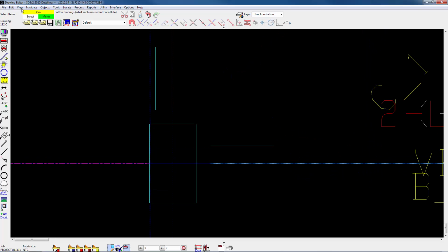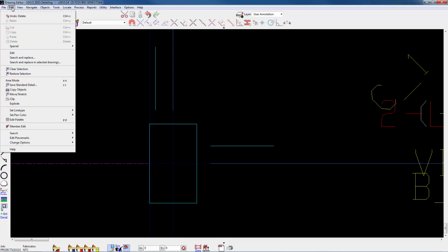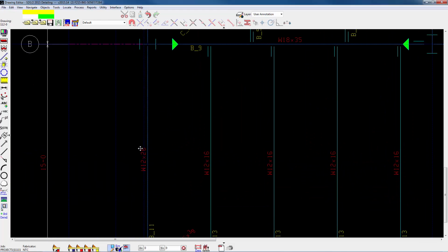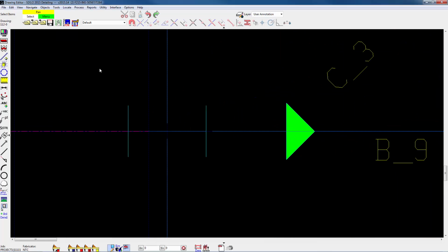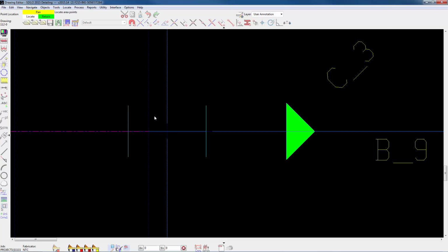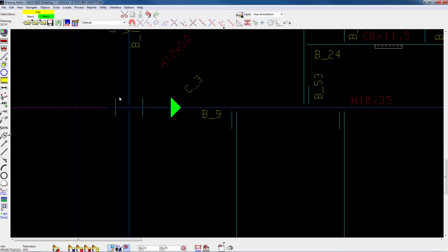We can use our clip command. So under edit, clip, and put a box. Wherever you stop this box is where it's going to clip it to. Now it's saying clip inside, outside, or cancel. So I'm going to say inside. And draw a border around it, no. And it clipped that line out of there. So same thing here, if you wanted that clipped out of there. Okay, so now we go back to edit, clip, inside, draw border, no, and we clip that out.